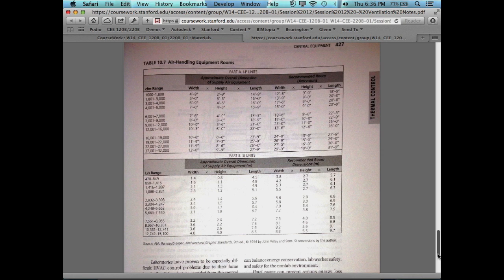A very important thing with these, though, is you like to have pretty clear air space all around it. So if you put an incredibly nice hedge all around it, it blocks it from everything, and you could really decrease its efficiency because it can't get the air flow through it that it's supposed to be getting to do what it needs to be doing.